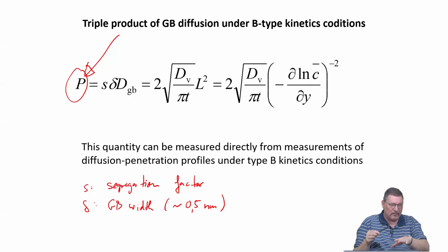I suspect, as I showed you for the pure copper, that small deviations in inclination and misorientation of these boundaries serve to have different structural units with different distribution of excess volume, which means the local chemical potential for segregating species to go or not to go to these places will be different. And this is what we see in the end without having detailed knowledge of the reasons, but it's, I think, a good concept to work with.